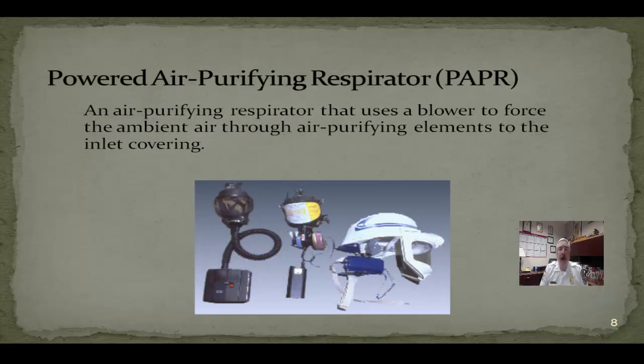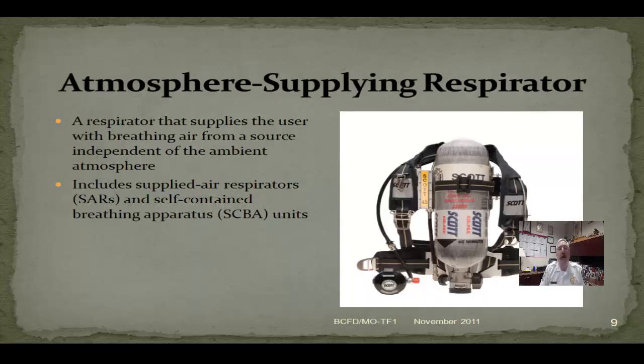With a powered air purifying respirator, or PAPR, this is an air purifying respirator that uses a blower to force the ambient air through the air purifying elements and directly into the inlet covering of either the facepiece or the hood, depending upon the unit that's used. With the Missouri Task Force 1, we have PAPRs that are part of our hazmat kit. Then there are atmosphere supplying respirators. These are respirators that provide you with breathing air independent of the atmosphere in which you're in.